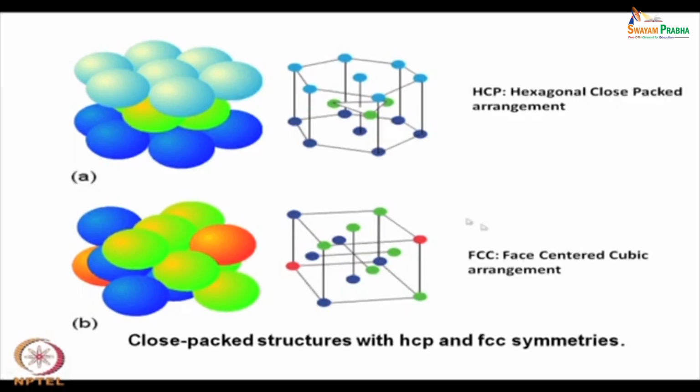For example, here in the hexagonal structure, all the horizontal planes are slip planes, and horizontal planes are close packed planes, whereas the vertical ones are not close packed. Vertical ones are open, and therefore, if the atom has to go to its next equilibrium site vertically, it has to move this much, whereas in the horizontal plane, if the atom has to go to the next equilibrium site, which is this one, the distance of separation is much less.